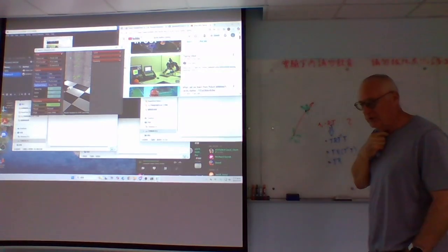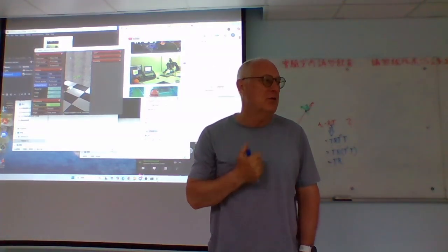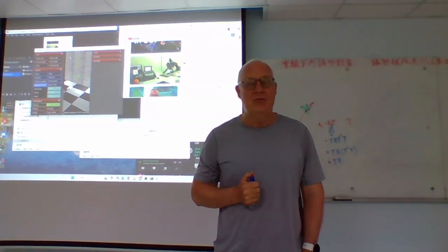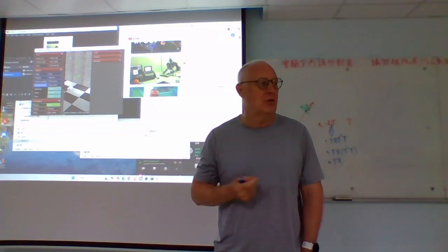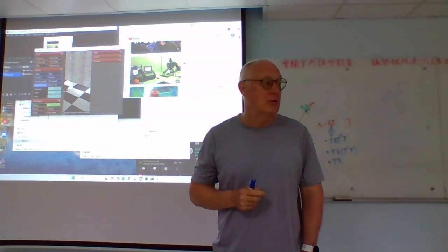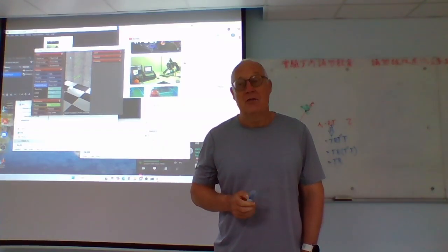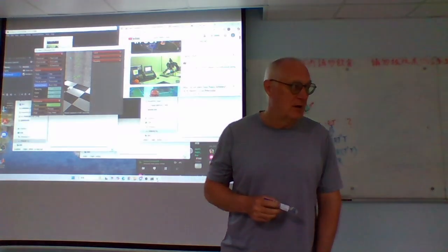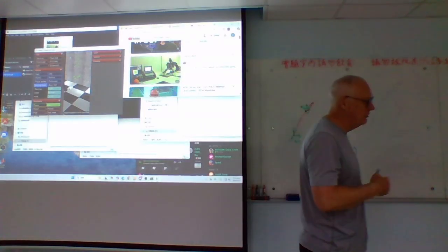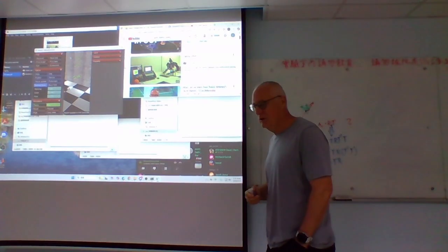The good news is once you have forward kinematics, you can at least approximate inverse kinematics very easily. Then you can use the Jacobian inverse or Jacobian transpose methods, and that'll give you a good solution to the inverse kinematics. That may be all you need. Sometimes, if you are limited in the processing power, then you may need to use an analytical solution. Sometimes you have a domain where you need to worry about singularities in your space.